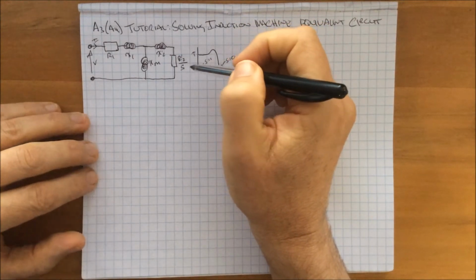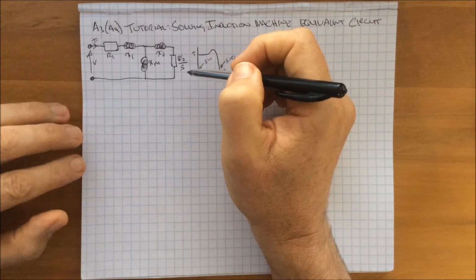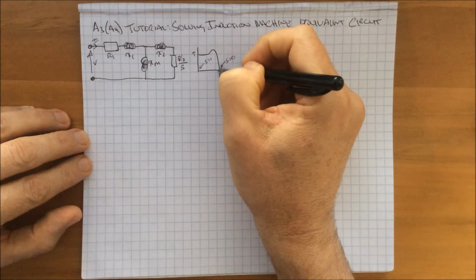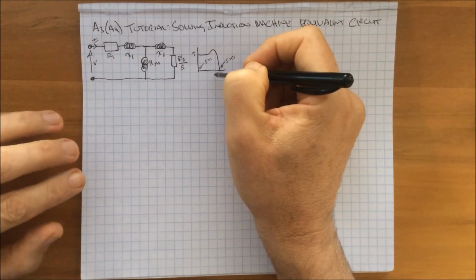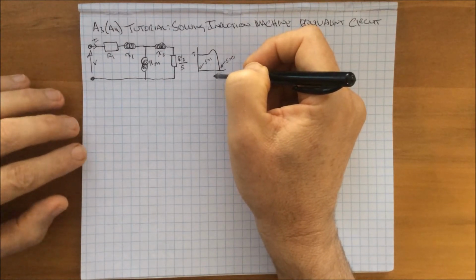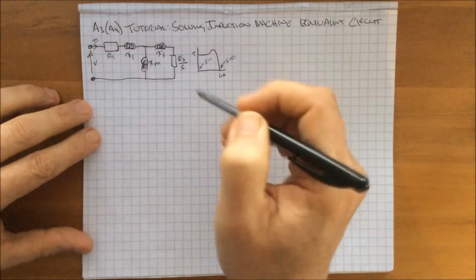The third test we can do is to run the machine up to speed with no load. And so we'll be operating it up about as close to up here as what we can get. Those three tests and the numbers we can get from that, we can then use based on these equations to solve for this, and that's what we'll do now.